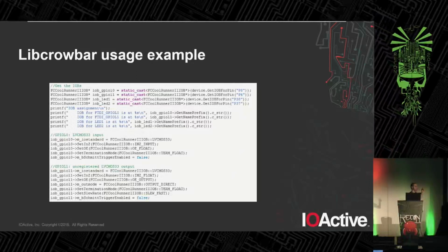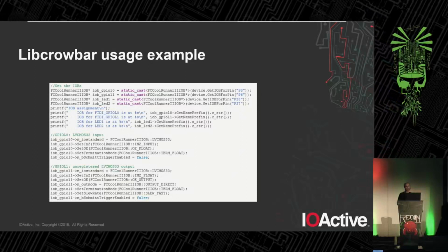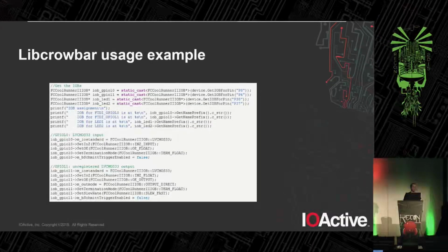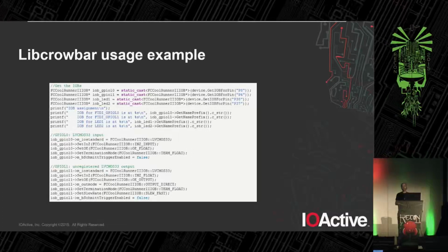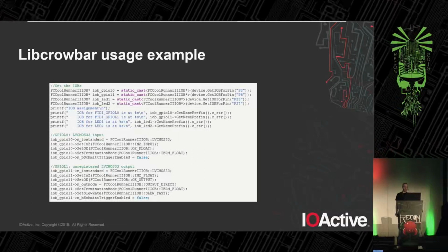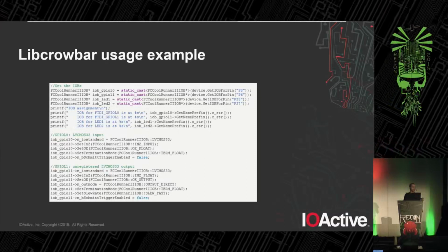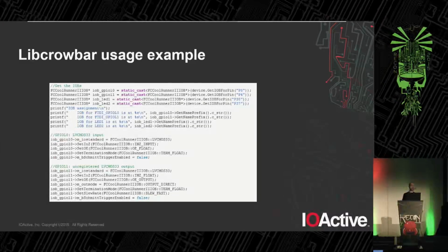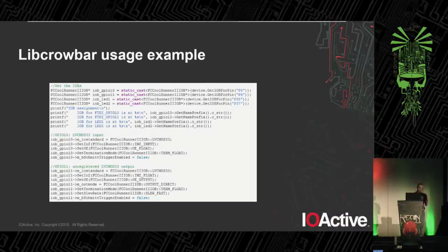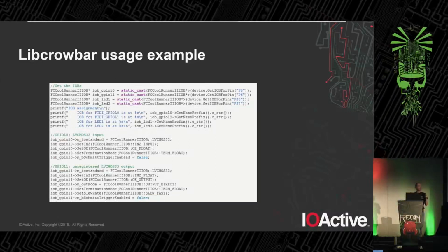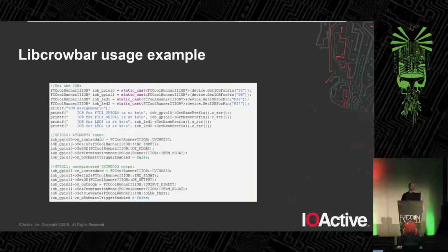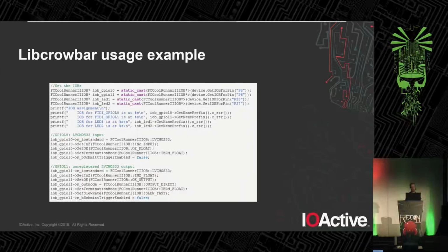I can pull up full source if anybody's interested in looking at it. But the end result is that I can go from an in-memory technology map netlist created like this as C++ objects. I can then place and route this, produce a valid bit stream, flash the device, and have it work. I can also go the other way around. I can go from a programmed device, I can read out the bit stream. I can turn it into an ASCII art schematic, and I can turn it into synthesizable Verilog, as long as you're not using the features I haven't yet reversed the functionality of.